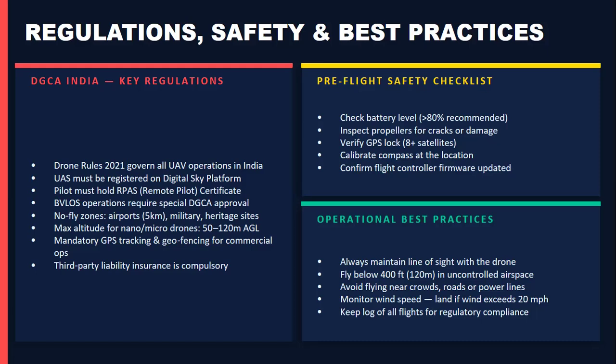Before every flight, pilots should inspect batteries, propellers, GPS connectivity, and system calibration. Maintaining visual line of sight, avoiding restricted zones, monitoring weather conditions, and keeping flight logs are essential best practices for safe and compliant operations.